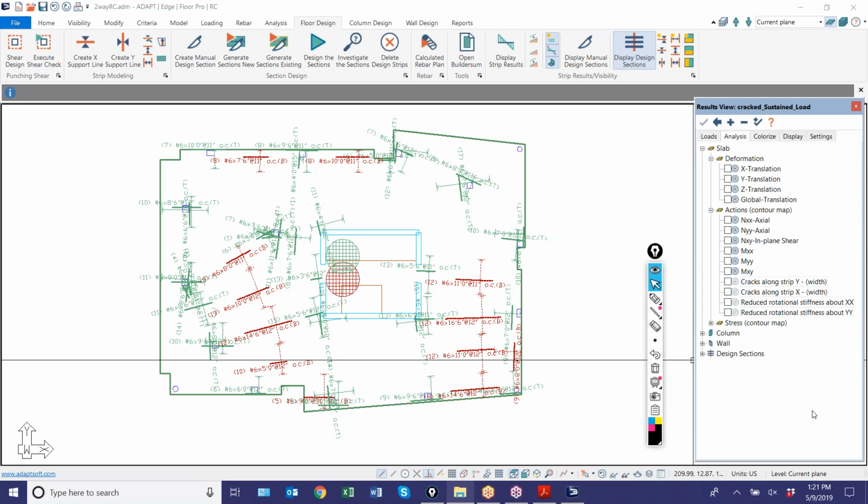in terms of a long-term multiplier, there is a correction factor that uses the contribution of compression rebar. Our long-term multiplier doesn't consider that, but the actual cracked evaluation of every design cut considers the rebar only for the calculation of the cracked moment of inertia.